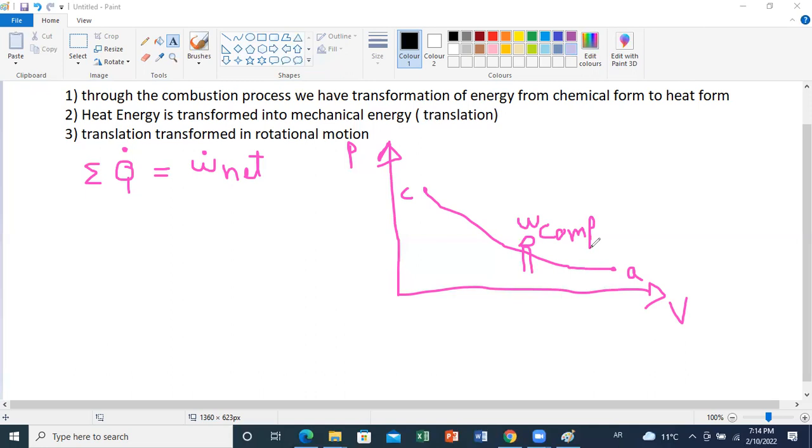It will continuously rotate. So during expansion, you will give it the required push to rotate, and enough energy to complete its rotation. When it's doing the other half of rotation, a part of this energy will be given to compress your air through the upward motion of your piston.